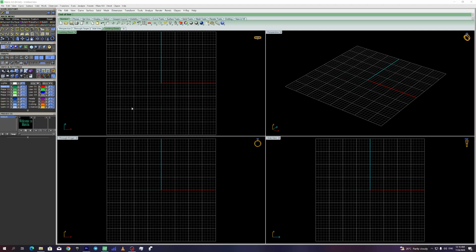Now, let's talk about selecting objects. When you left click on an object, it turns pink. That means it's selected. Once selected, you can easily move it around. But what if you want to copy it? Here's a great trick. While dragging the object to a new location, just tap the Alt key once, and Rhino will create a copy right at that new position. The key point here is that you need to tap Alt without any pause, just a quick, light tap. That's all it takes, and you can repeat this as many times as you want, copying the same object over and over again.